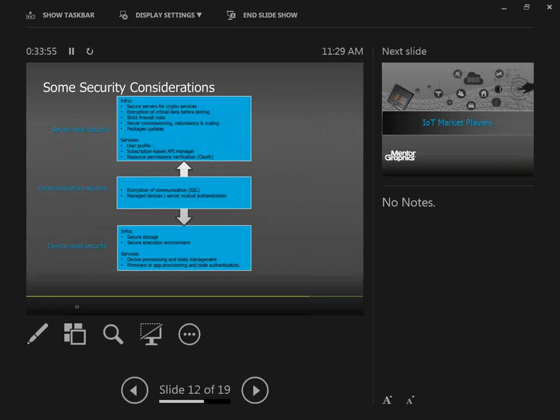Every device needs to have infrastructure for security. That infrastructure on the device means that the device needs to have secure storage and, as much as possible, a secure execution environment to carry out any kind of authentication and crypto security operation. Usually this is implemented in the form of a secure element, which is a special microcontroller with tamper-proof security.